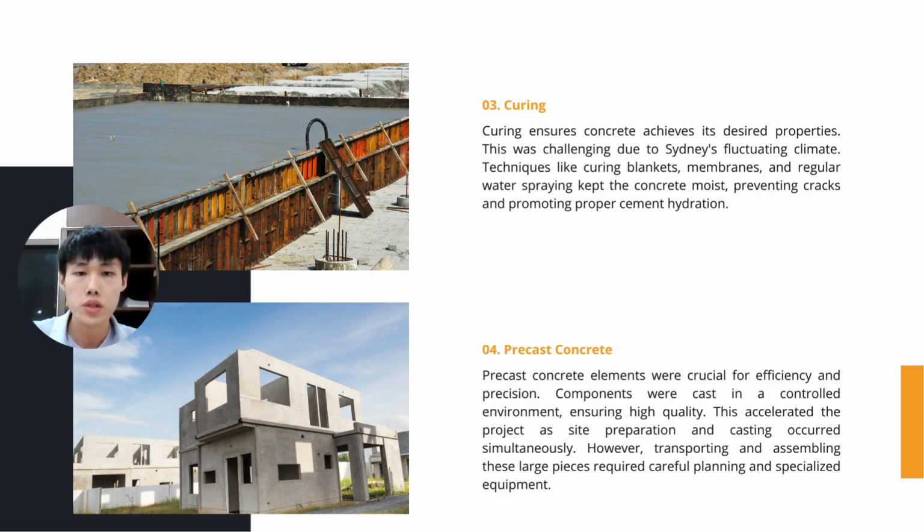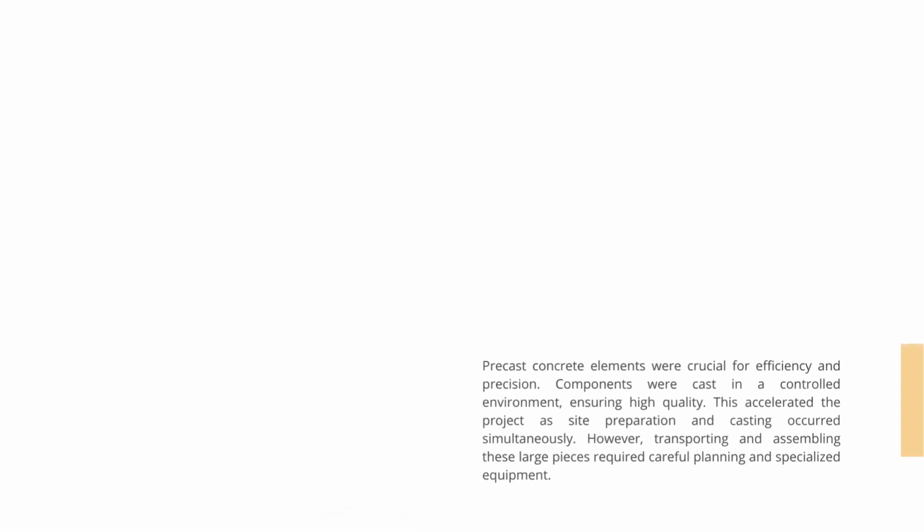Precast concrete was crucial for efficiency and precision. Components were cast in a controlled environment ensuring high quality, and this accelerated the project as site preparation and casting occurred simultaneously. However, transporting and assembling these large pieces required careful planning and specialized equipment.